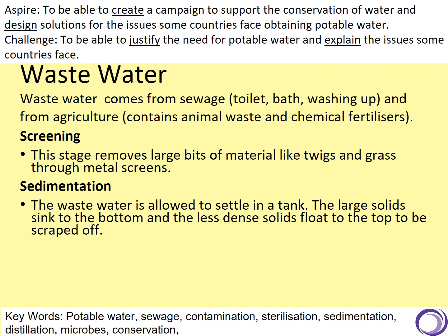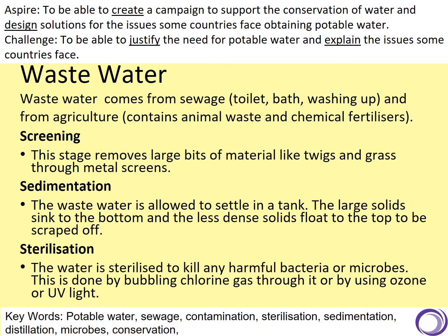It then goes into huge tanks called sedimentation tanks, and it's allowed to settle. And the large solids, because of gravity, sink to the bottom, and the less dense solids sink to the top and can be skimmed off. And what we're left with is the liquid water in between. That liquid water can then be sterilised to kill off any harmful bacteria or microbes. And again, this can be done using chlorine or ozone or ultraviolet light.